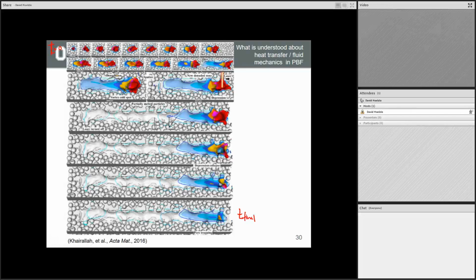But this is it turning on. You see then, the color corresponds to temperature. So reds are hotter, blues are colder, right? Okay. And then anything that is not really colored means it's solidified. Anything that has a color associated with it means it's in liquid state. Okay. So what you see here is you get this initial heating of the metal powder. You get also this